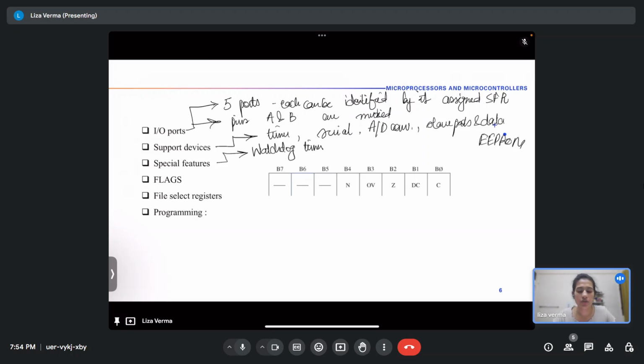So the motive is to automatically reset your system in case of any system failure, but with a given amount of delay. It's not always that your system will need a reset. Sometimes the system regains its normal operations, right? For that, the watchdog timer is counting up until that time, so you do whatever you can to correct whatever is wrong, but only until I get to my maximum count. If I get to my maximum count, I will reset the whole system.